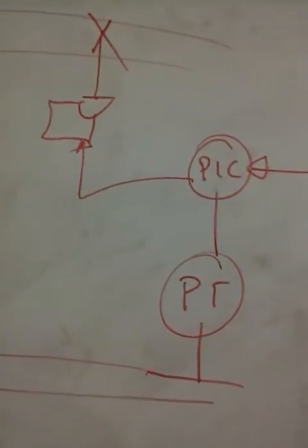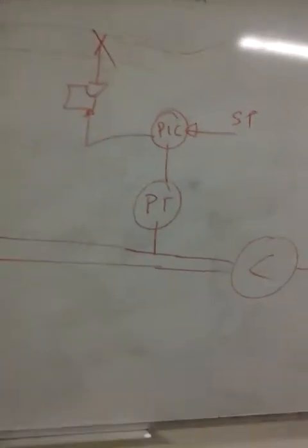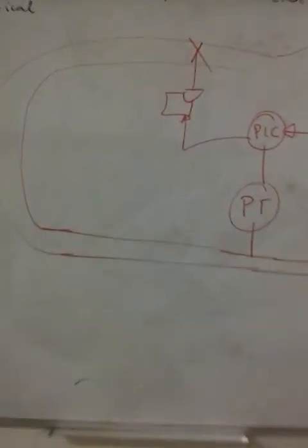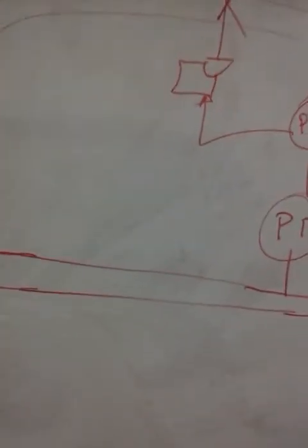Here, by opening or closing the control valve, the pressure in this tank will change. Usually if you open the control valve up to 100%, the pressure will decrease. Remember, there's a pump pumping water from the storage tank to the control tank. Okay. Then with this loop, we can still control the pressure in the pipe.